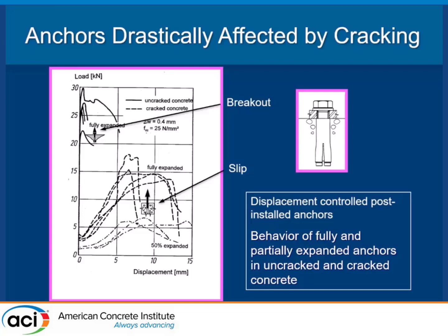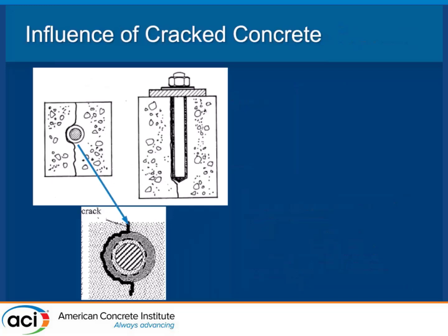This is that post-installed anchor that you put in. You cannot retighten. You lose like 50%, fully expanded. Let's say you put it in a little bit, like 50%, the reduction is even much less. So these things are kind of cautionary here, we're trying to tell you. And I'll get into a little bit the value of which we're trying to target when they give you values.